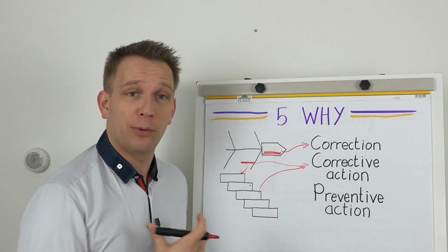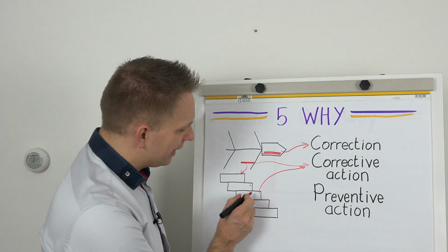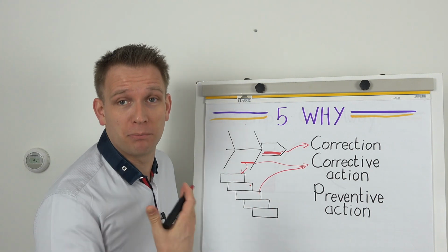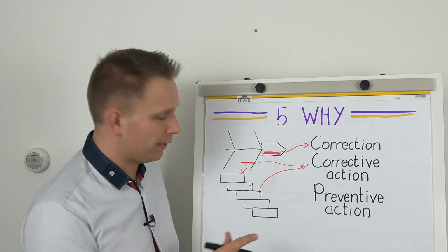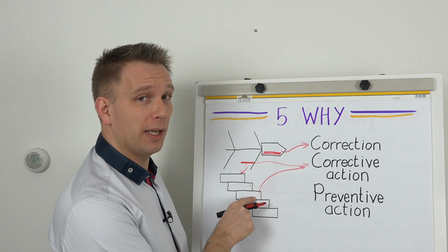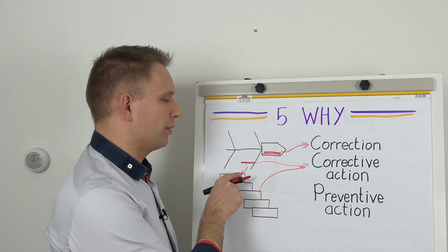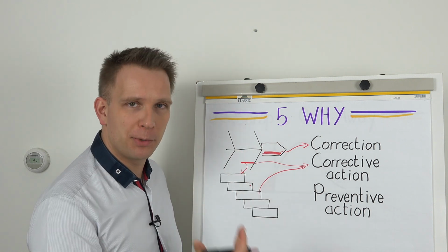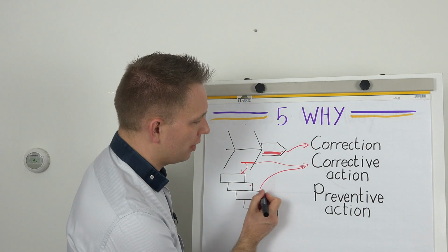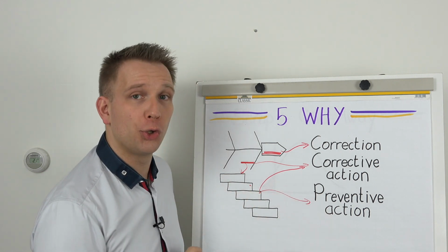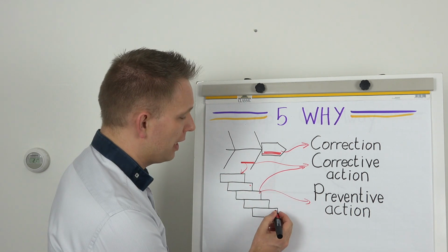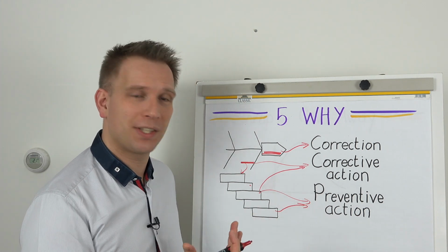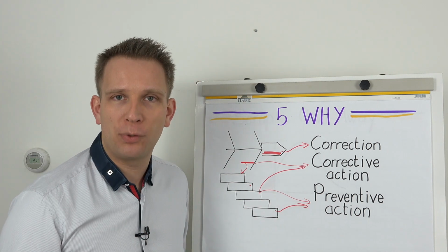And if we check where we can find preventive actions, well, that is also roughly in this middle part. You can in fact find preventive things, because quite often this underlying cause will cause both this problem, but perhaps also other problems in similar machines, similar processes. So here we will find a good point for preventive actions, and also, of course, that is where this whole root cause analysis comes from, the 5th why.